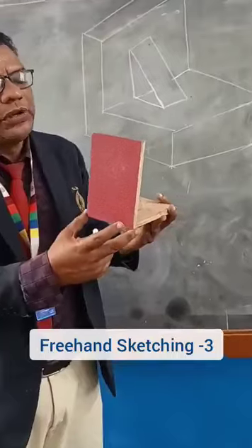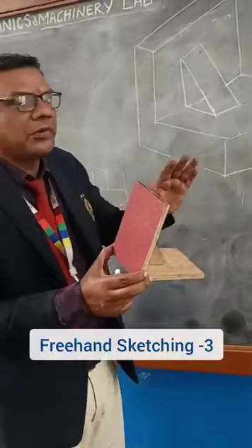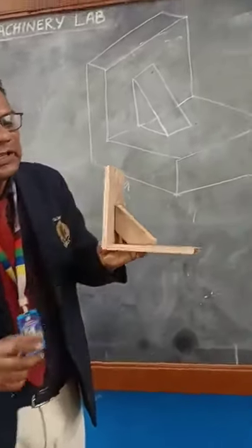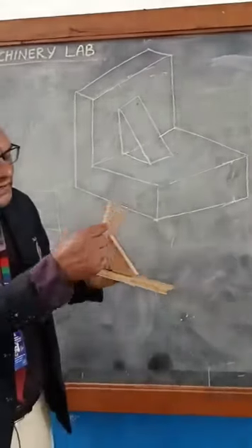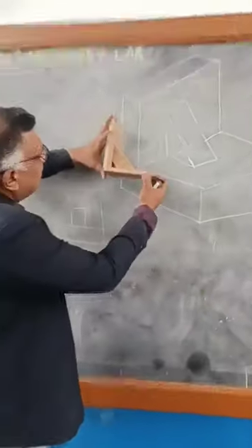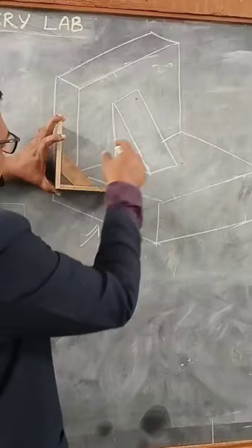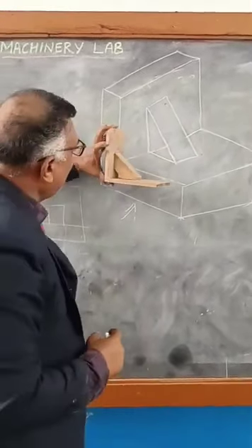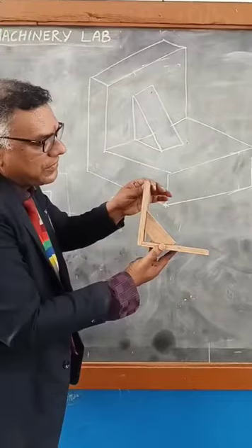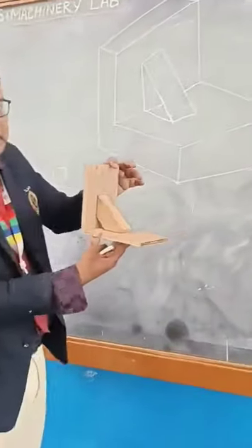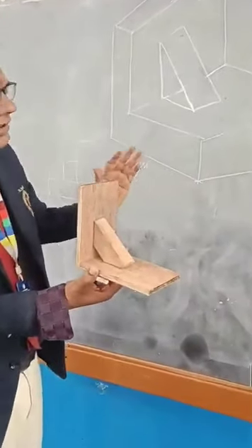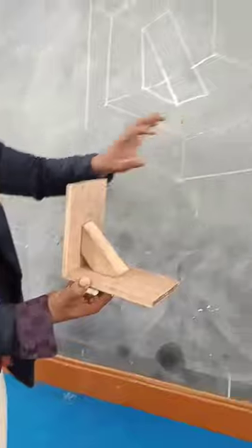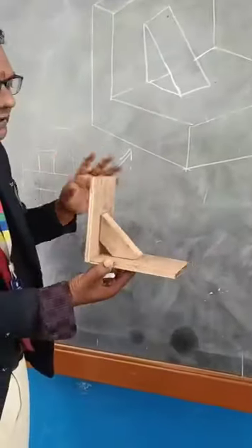The 2D model. The same thing I have drawn in a 3-dimensional way, having an L shape. So this is an L shape. It will be a 2D, and this part will be here. So now I am going to tilt it. Since it is 2-dimensional, I am going to tilt it at 30 degrees. For any isometric projection, it should be 30 degrees.